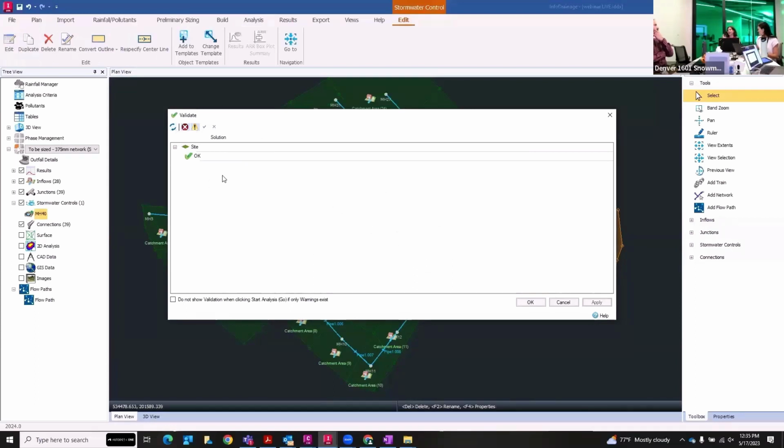Great. That is a feature you have in InfoDrainage that we don't have in Storm and Sanitary: being able to check it before you actually run the design. In SSA, you have to run it before you know why it won't run. I like this. It's nice that if you click on it directly from this menu, it opens the pop-up where you can make those changes, rather than getting a warning and then having to figure out where exactly that change is. Obviously, adding rainfall data is a pretty obvious error, but this can be nice for more specific errors that you might be having.